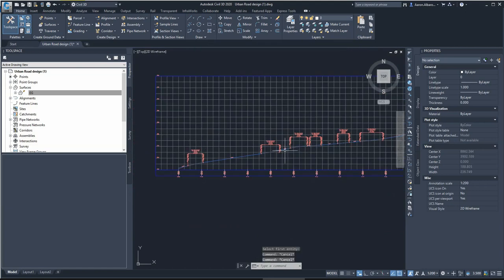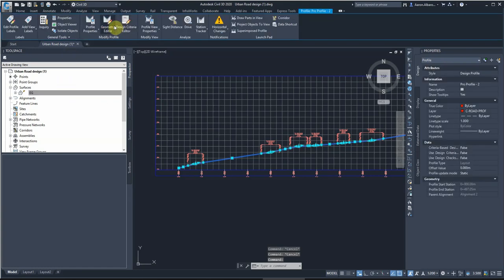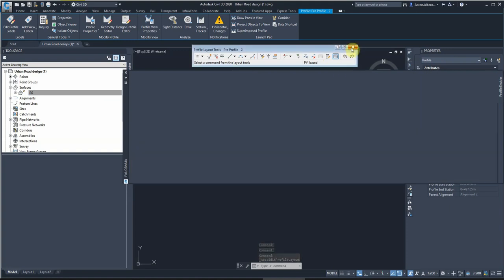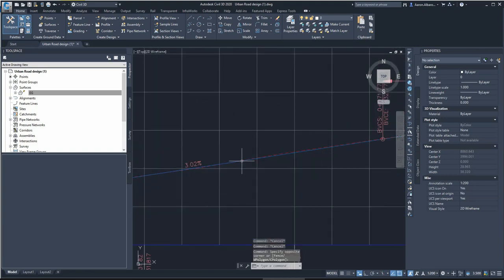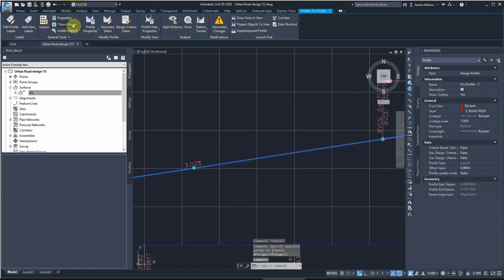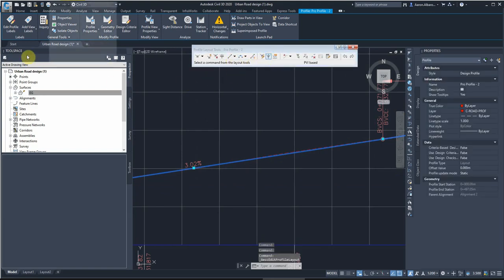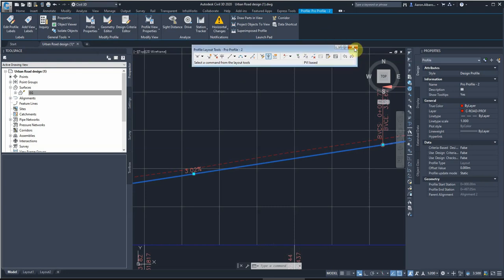That's all looking good. Just to make sure, I'll go back and check my K values for the last time. Geometry editor, and my K values, all of them are larger than 10, that's fine. Okay, all good. So the last step I need to do, as we agreed, is move it down by 150 millimeters. So geometry editor, move the entire profile. It asks me, do you want to move the entire profile or some stations? I'll move it all. -0.5, enter, and that's moved down.